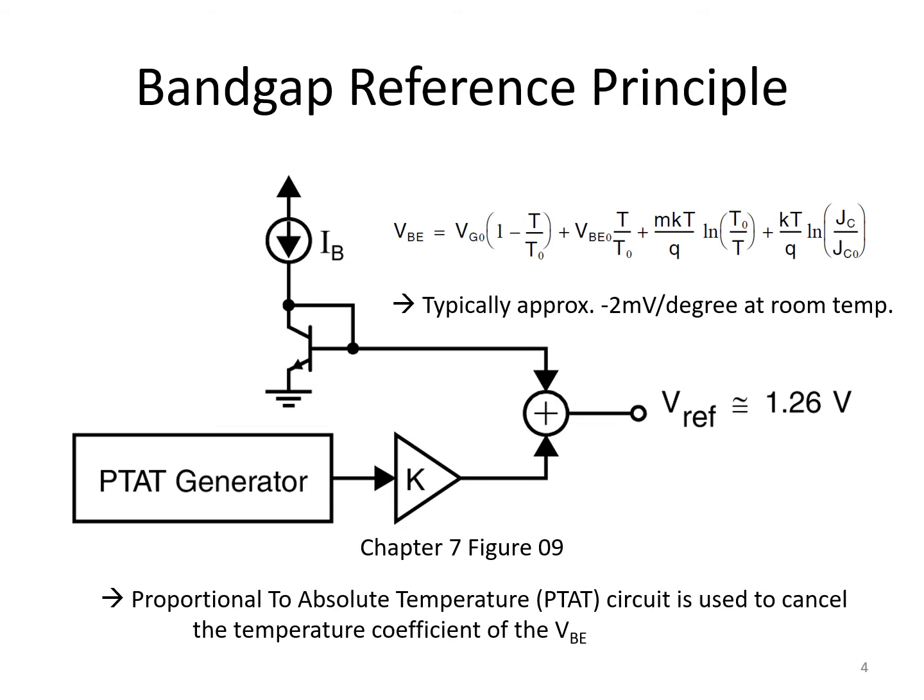So although, as we said, there's many different clever circuits developed to generate a band gap reference, most of them are based on the same principle. And it begins by looking at the forward voltage drop across a PN junction. Now you can realize that as a diode or a bipolar transistor. Even if you have a CMOS process, it turns out that you clearly have PN junctions everywhere.